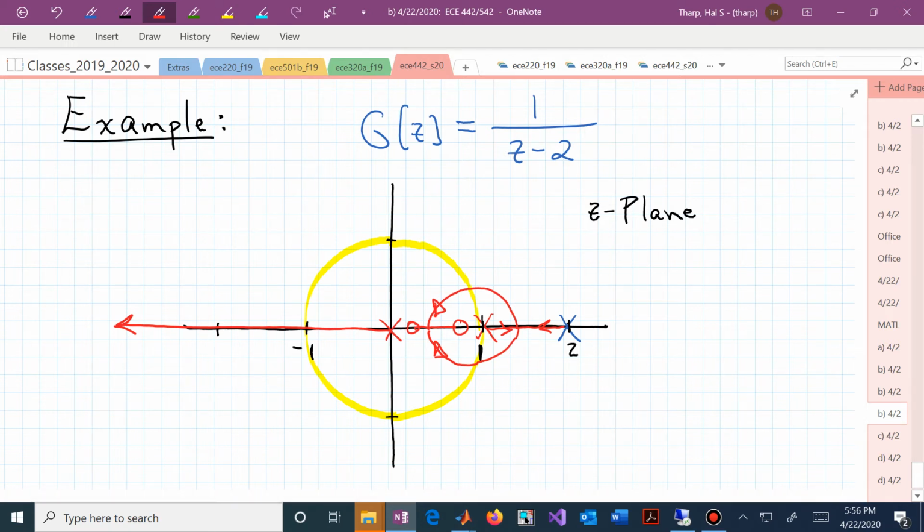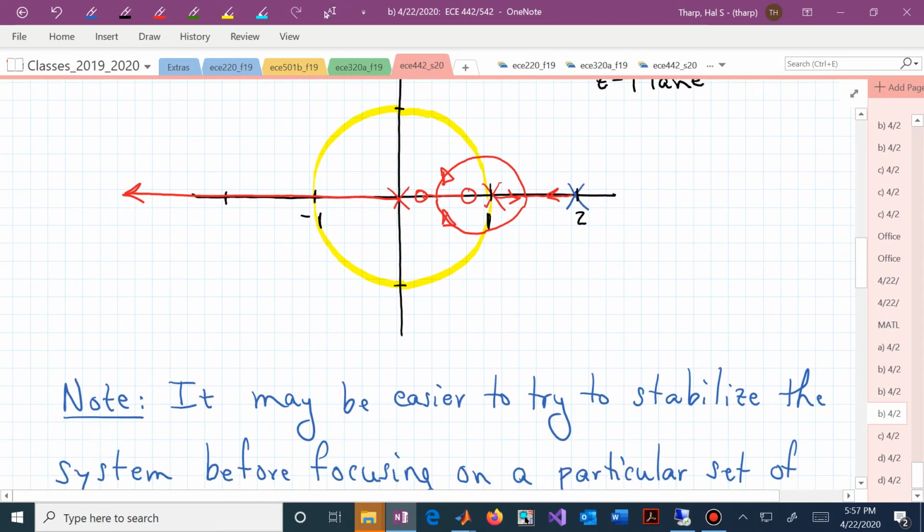But now we've reshaped a little bit the behavior of our root locus diagram by introducing an additional pole and an additional 0. The pole is fixed at the origin. The other 0 now can be adjusted, and maybe we can slide this rightmost 0 a little to the left so that the triangles, or the closed loop poles, end up further inside the unit circle.